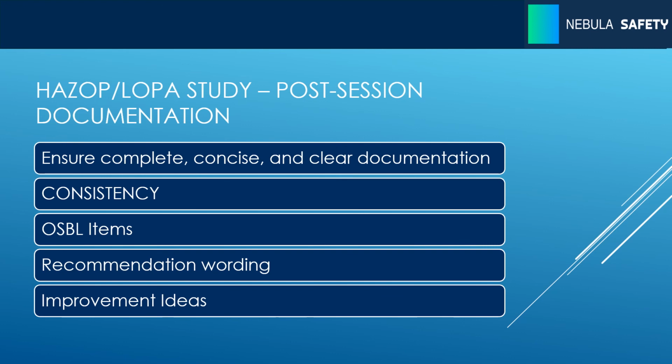Any issues with the PSI documentation, so not just the P&IDs, the CNEs, the seismic studies, anything like that should actually be captured as a regulatory-driven item. Once again, within the words regulatory-driven, it means if they're incorrect and you get audited, there's going to be an issue. So we want to capture them in the PHA. They're not nice to haves, they're things that the facility needs to do as part of the overall recommendation structure.